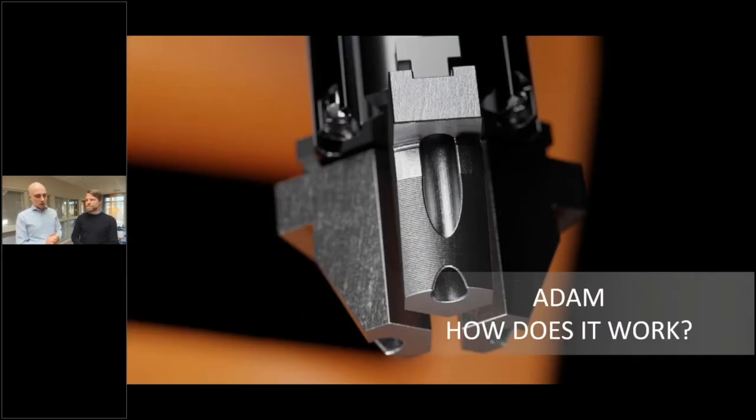So the next one is also under the melt materials. It's called ADAM, which stands for Atomic Diffusion Additive Manufacturing. Which is basically an FFF technology, but instead of printing plastics, you have a plastic with metal powder bound inside. So you print it the same way as you do with FFF technology, but the part then is made up of 80% metal.